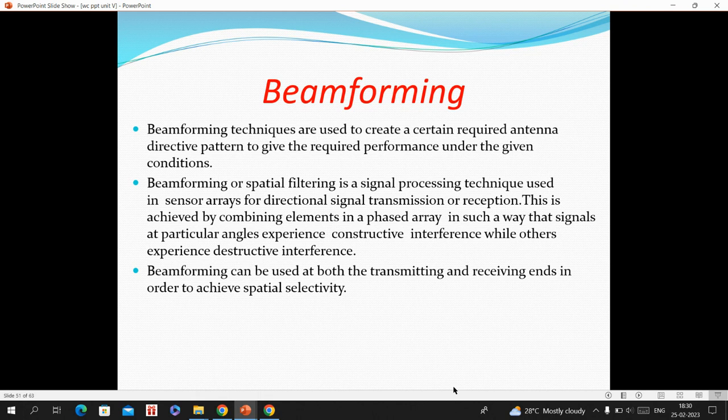Consider a base station that has only one user at that particular time. Instead of transmitting the signal in all directions, the base station can be adjusted to transmit power only to that particular user alone. By that, the entire power of the signal reaches the user, so efficient power transmission is achieved with the help of a beamforming technique. It is a process of transmitting an electromagnetic wave in a required direction instead of all the other directions.